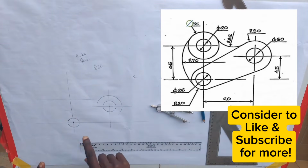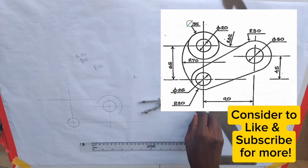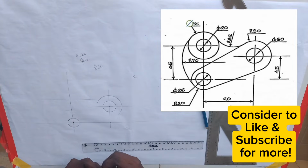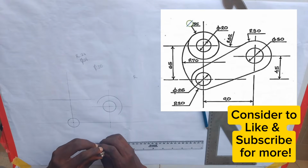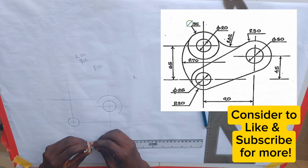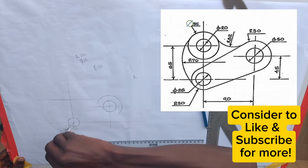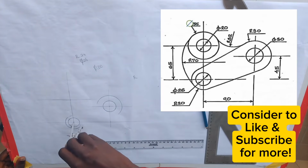Okay. Then for this side too, we have another arc. You can see it is given the radius of 20. So that will be 2 centimeter. That is 20 millimeter, that will be 2 centimeter. So I'll measure 2 centimeter from my ruler. So I will mark an arc here. As I've said, it's not a complete circle.